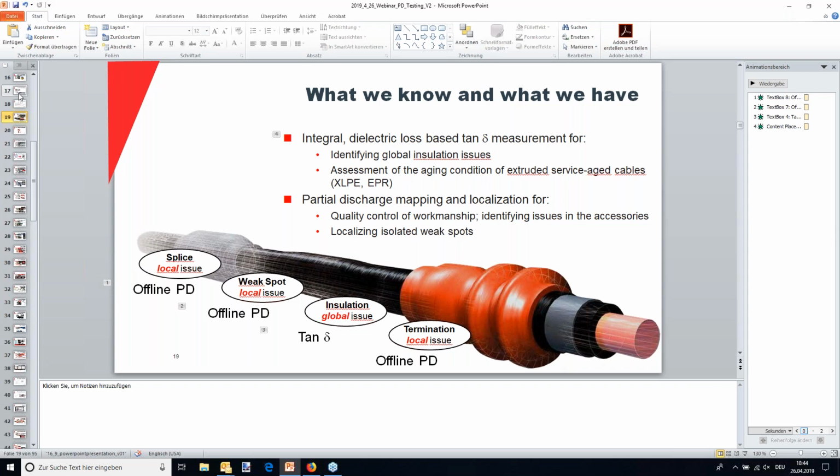I mean, every method has its limits, but that kind of localization based on TDR and traveling wave and this reflection analysis is already better than anything else in terms of a real measurement. You can see really far into the cable, and depending on the cable, it's, rule of thumb, on average 2, 3, sometimes 5 kilometers. Sometimes 10, depends.